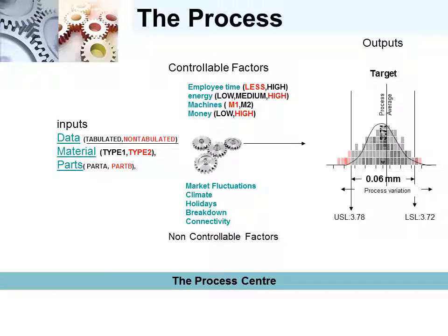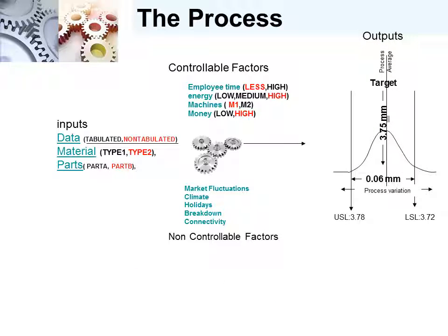There are these two objectives for a process. The quality characteristics should be both centered as well as with low variation. If you notice in this process output, the data is not centered and the output normal distribution is moved away from the center. Like spread, centering is another measure of a process output. The centering is also called the accuracy or closeness to the center.